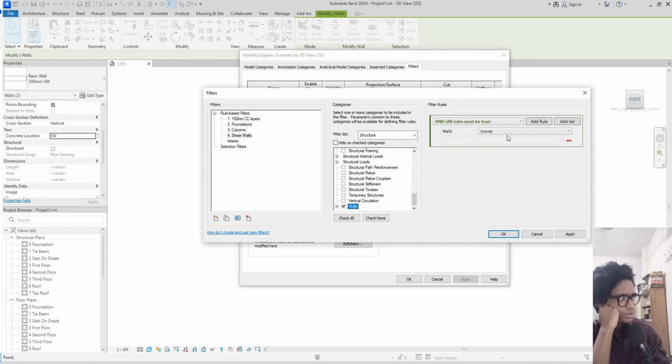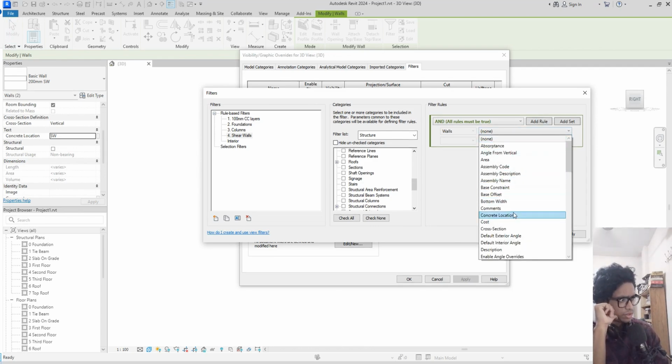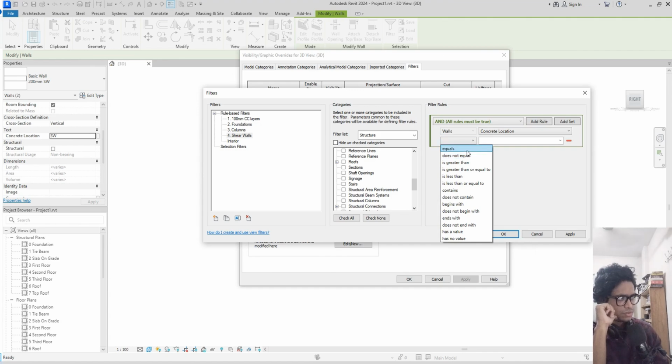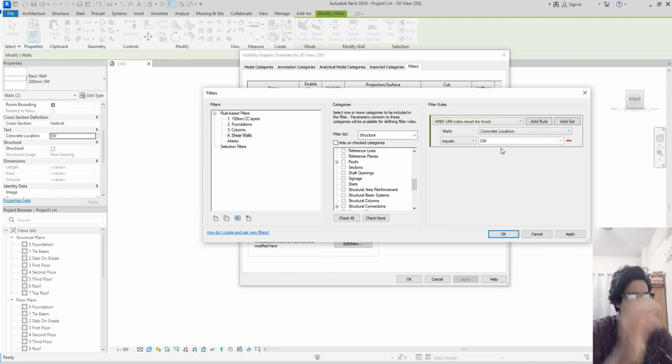Shear walls, it will be in wall category, and there's no option available for structural wall, because structural wall will bear the load of the structure, but walls mean there might be architectural wall, like the partition walls. They are the architectural wall because they deal with the space and aesthetic. They literally don't bear the load, or maybe they bear a very small amount of load. Okay, wall category will be fine.